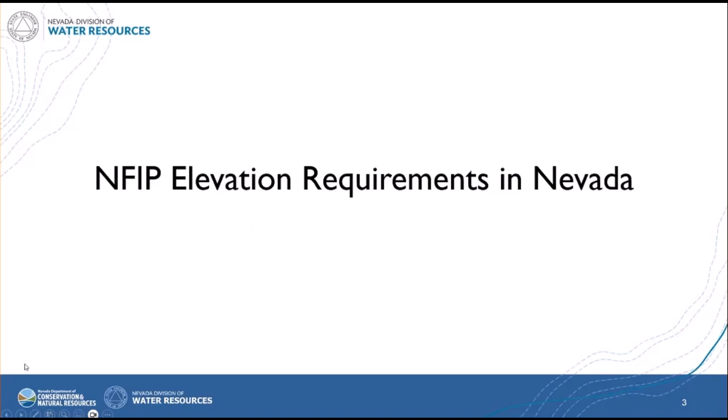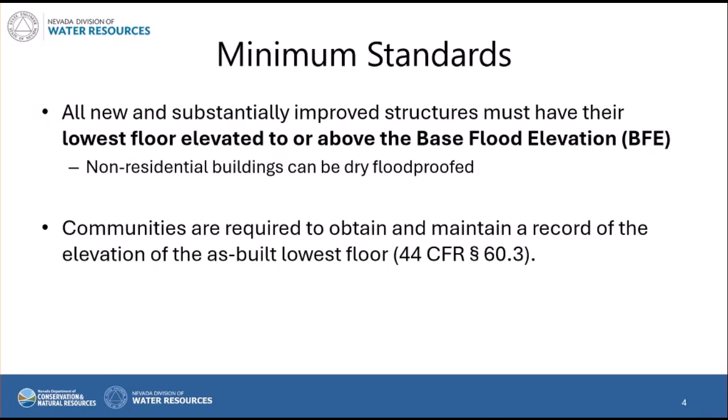And really the reason that we're talking about elevation certificates today is because it helps you tie back to the minimum National Flood Insurance Program standards for elevation of buildings in that special flood hazard area. These are the requirements in your local ordinances and building codes.